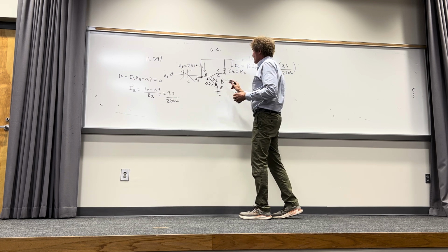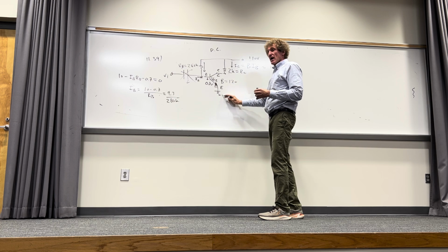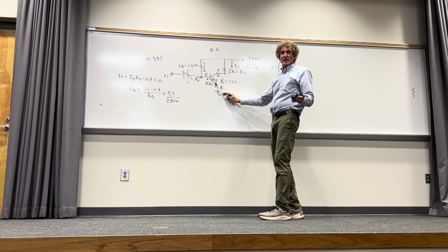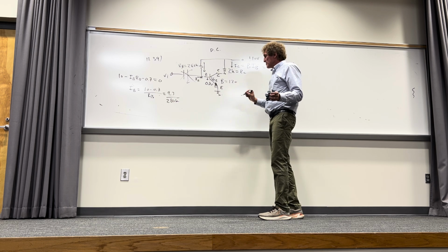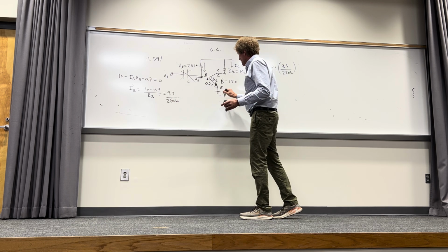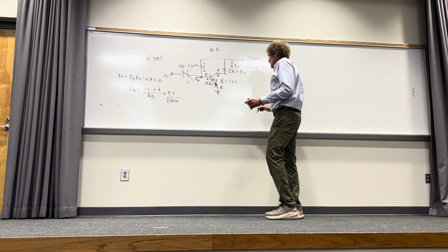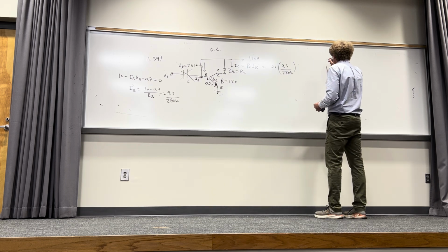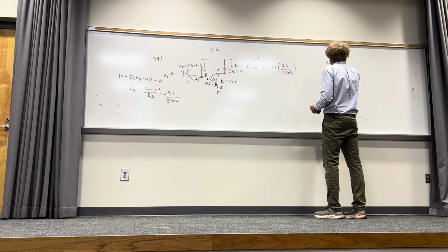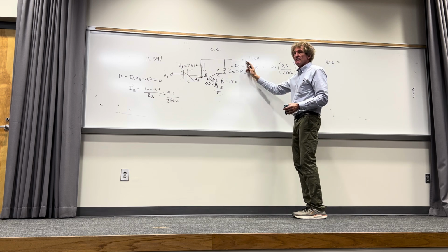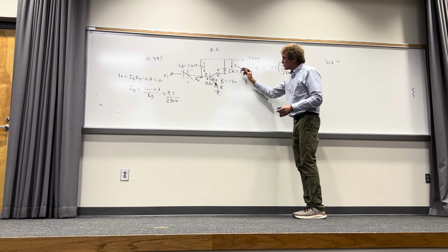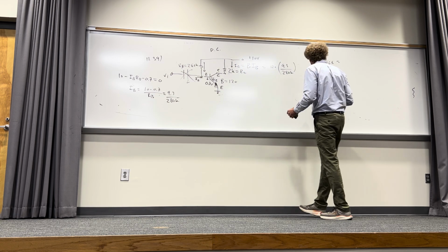Then, if I want the voltage at the collector to ground, remember the emitter is grounded here. Can everybody see this, by the way? That's a ground symbol I'm trying to show you. Right there. Now, if I want voltage collector to emitter, here's what I do. I know there's 10 volts here. I'm going to do a voltage loop again, but I'm going to subtract off that voltage.